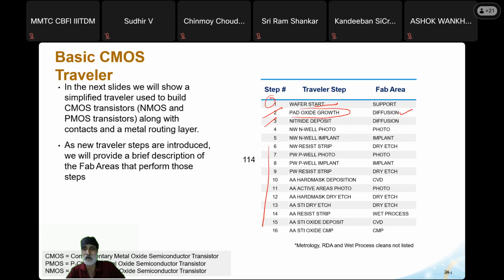All that information will be in a process recipe, which is stored in the machine, and the recipe has a number. That information will be in the traveler, and once the technician gets a set of 25 wafers, he will program that particular recipe, because he will have this information in the traveler, and the recipe number will be there.